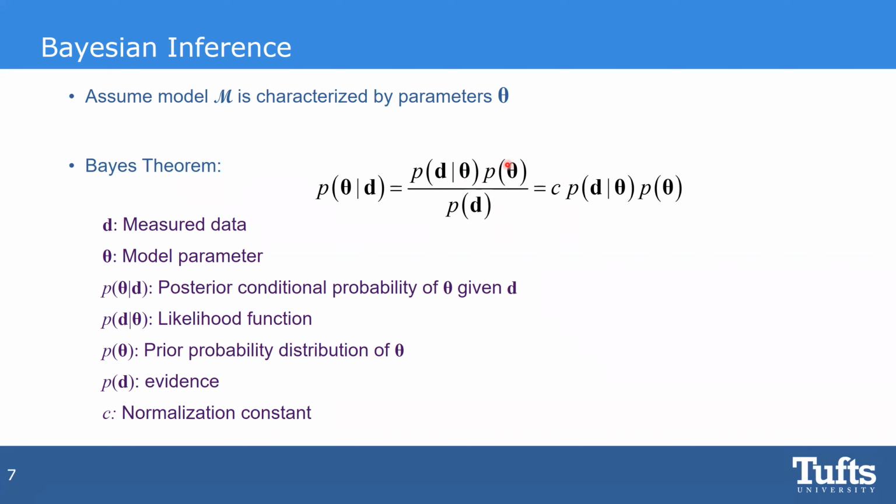GE wouldn't give it to you. Let's assume that. So you have a prior assumption for that. Then you have some measurements, you put some accelerometers, and the prior knowledge gives you the prior probability distribution. The data gives you the likelihood, and you multiply these two together, it gives you your posterior. That's it. That's Bayesian inference.